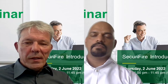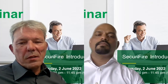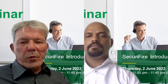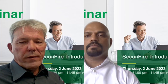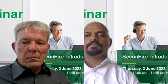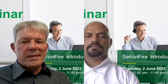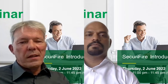There is one that came in again. Are the extinguishing outputs approved? Yes, all our extinguishing outputs on our panels, or even the interface, are fully approved according to EN regulation. Yeah, exactly, VdS certified. I mean, VdS tested our system for extinguishing systems according to EN 12094, which is actually an EN regulation.